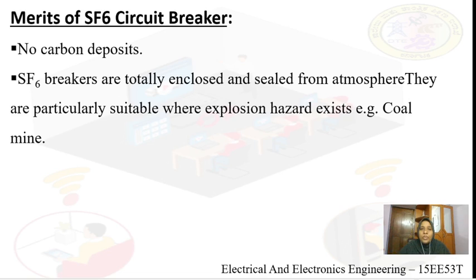Once there is a small gap, the circuit breaker will understand it as though there is a fault. When the fault is there, only then the moving contact and your fixed contact will separate. When the system is healthy, they will always be in close contact, touching each other. Now because of carbon deposit in between the contacts, they cannot touch each other. The deposits are making a hindrance for them to touch.